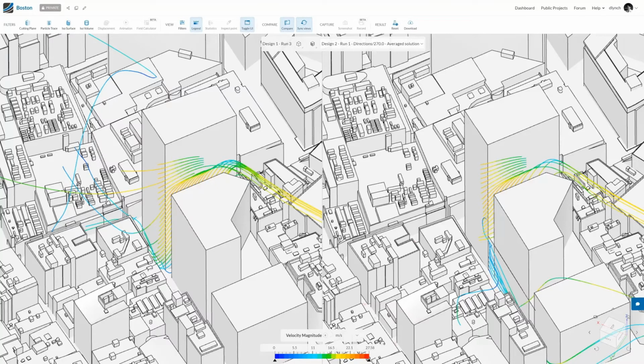And we're visualizing three-dimensional results, so the streamlines, or the direction or flow pattern in 3 dimensions, around the buildings that we're trying to design. And the key thing that we should be looking out for here is the downwash effect. So the downwash effect you can visibly see here is flow coming up to the building, being washed down by the larger building, and on the left hand side on design 1 we've got flow going down to pedestrian level and exiting outside. On the right hand side, design 2, you can see that no flow gets down to pedestrian level, and in fact any high speed flow exits a lot higher than the original design.